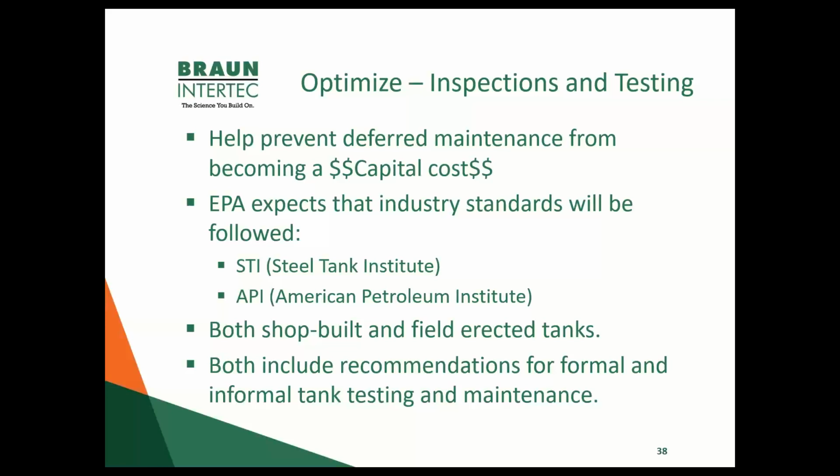So, optimizing your inspections and your testing. Everyone has to defer maintenance at some point, but you want to keep an eye on that, making sure that deferred maintenance doesn't become a large capital expenditure in the future. There are standards as far as maintenance protocols that EPA generally references as industry standards. Steel Tank Institute's one of them, American Petroleum Institute's another. They apply to both shop-built and field-directed tanks. They have recommendations for a formal inspection of those tanks to ensure that they are still serviceable.